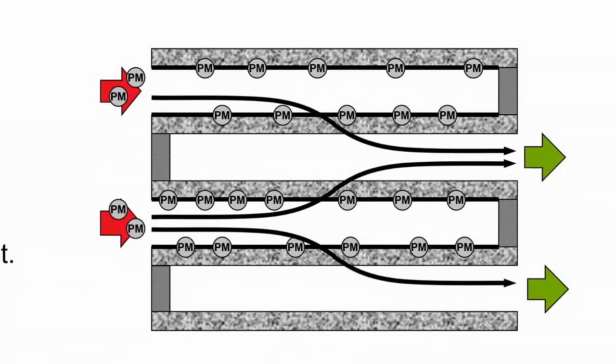We do those subtle regens when the temperature's high enough. Major regens will be done on a vehicle that's driven over 30 miles an hour for over 30 minutes, so we get the temperature hot enough under normal running conditions. It can do these fairly good regens. At some point, if the vehicle conditions aren't met enough times, where it doesn't reach that 30 miles an hour for 30 minutes and the temperature's not hot enough, like low-speed city vehicles and so on, it may have to come into a repair shop to have a stationary regen done.